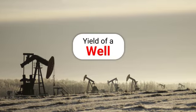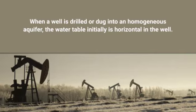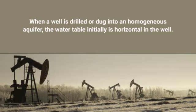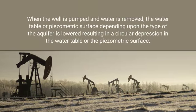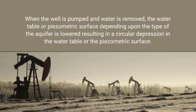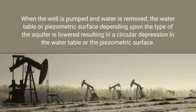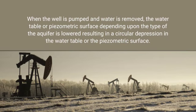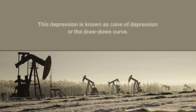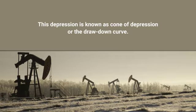Yield of a well. When a well is drilled or dug into a homogeneous aquifer, the water table initially is horizontal in the well. When the well is pumped and water is removed, the water table or piezometric surface, depending upon the type of the aquifer, is lowered, resulting in a circular depression in the water table or the piezometric surface. This depression is known as the cone of depression or the drawdown curve.